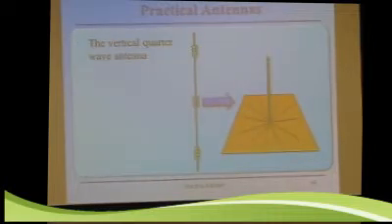And recent research has shown, in this particular case, when we were showing just a minute ago, this kind of assumes that these are all quarter wavelength, because we're taking this half of the antenna and putting it out as radials. But it has been shown now that if you can get 2 or 3 quarter wavelength, if you can get a bunch of even shorter ones, that helps a lot. Research published in QST in the past year or so has shown that you'd like to have 2 or 3 full-length radials, but if you can't get a bunch of full-length radials, if you can even get a lot of short radials, that makes a tremendous difference in how efficiently the quarter wave works.